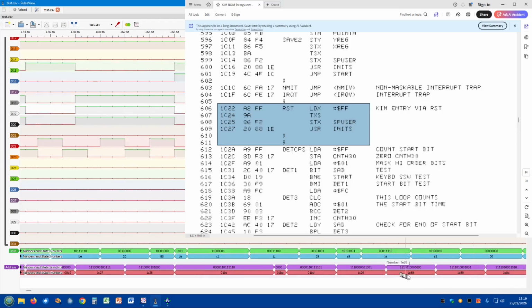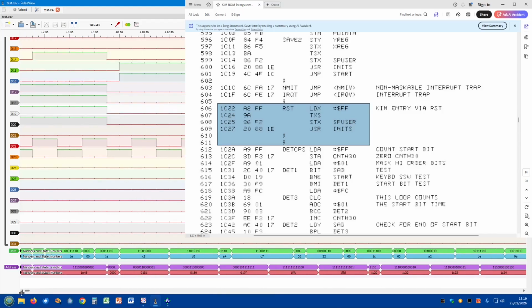And we actually jump to the address subroutine 1E88 there, which has got A2 on it, etc. But the processor then goes off and does goodness knows what. We know it's running, but we've got the wrong return address on. So when it returns from there, it's going to return to the wrong place, and it's going to be all over the place. We need to fix those bits.